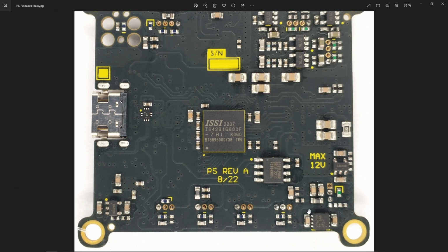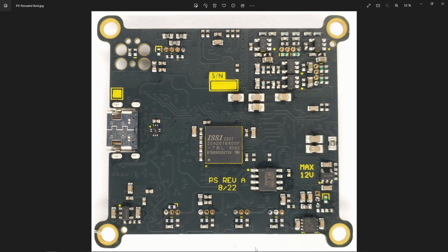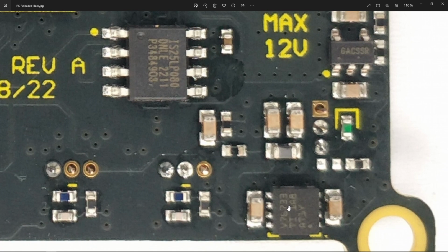But there are of course caveats to that, as we'll see, specifically with power wasted and thermal issues. What you might also notice is that these parts are very, very small, even given that they can handle up to about 0.5 amp and 1 amp within certain conditions. A switching regulator will require far more parts, inductors, large output capacitors, maybe even the MOSFETs and diodes themselves, whereas these LDO regulators simply, and a lot of the times, require input-output caps and maybe some feedback or filtering circuitry.